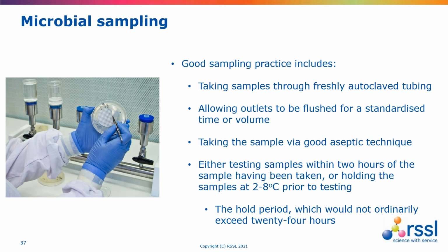That degree of extreme biofouling is very, very challenging indeed, and nobody really wants to be in that situation. It's also important in terms of good practice, if we're rinsing when we're cleaning equipment, to ensure that we have effective cleaning validation. And part of effective cleaning validation is segregating clean equipment from dirty equipment and avoiding the aerosols from dirty equipment recontaminating clean equipment. That kind of goes off down a cleaning validation route, but it's just another important control measure to consider.